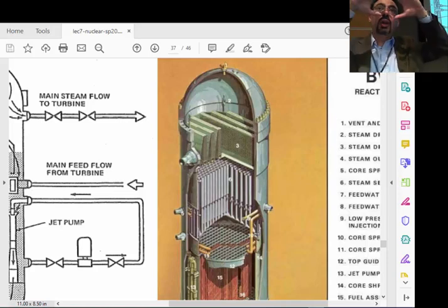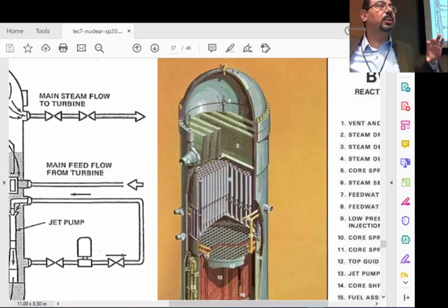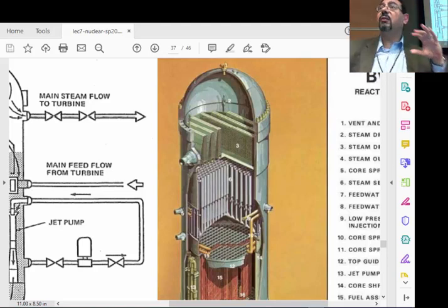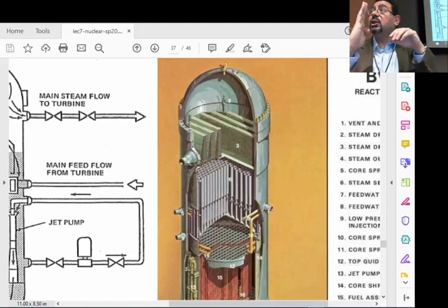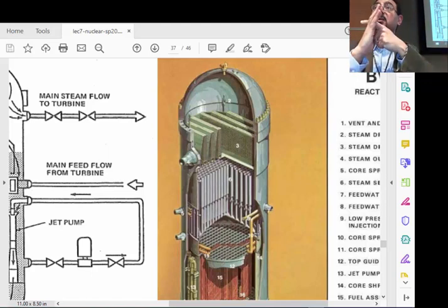So at the end of the steam drum on top of the boiler, before you send the steam to the turbine, and the turbine has plates rotating very fast, you want to capture any flying droplets with the steam. So you build this so that basically the steam only goes through and droplets get hit by the wall and drop down.